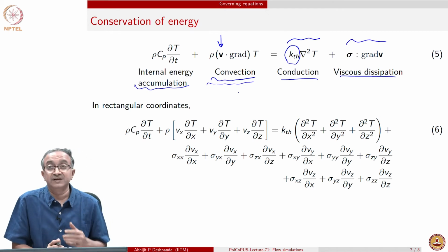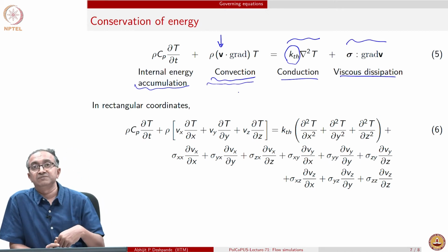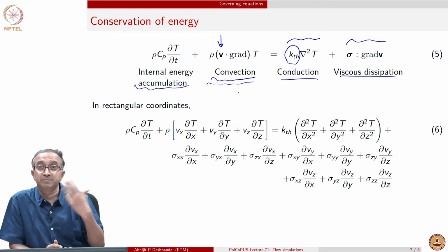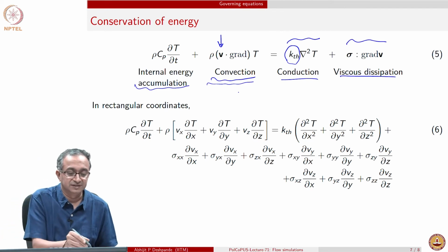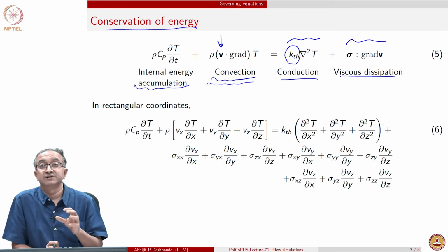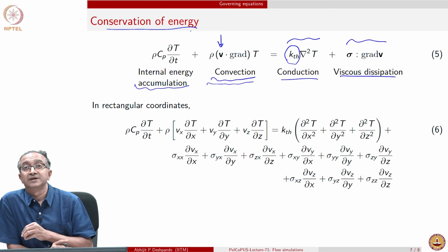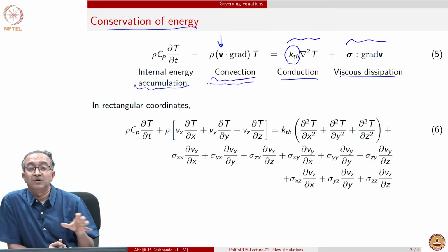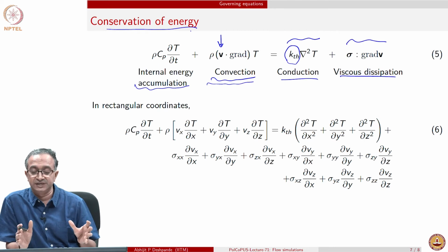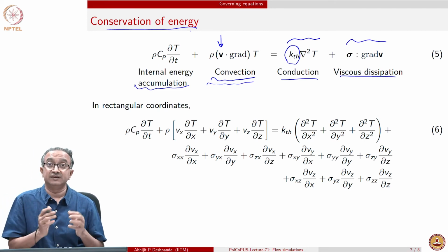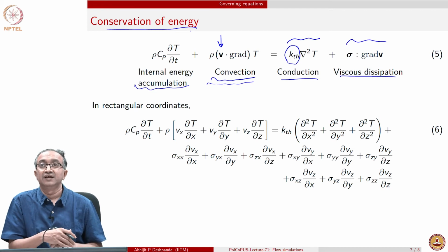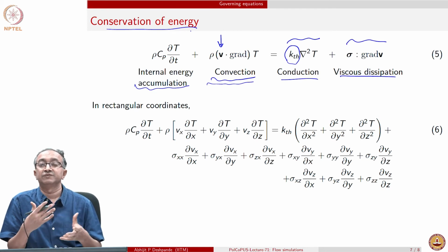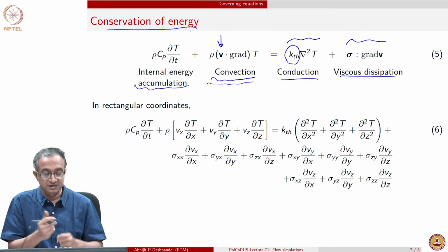At the same time, even convection may not be always easy to achieve, especially because turbulent flow and rapid mixing is not possible in case of polymers. So, you can see why there is a very great relevance for conservation of energy in polymer processing operations. With heating, cooling and all the other processes where temperature is changing and we have high shear rates and very high viscosity, the heat generated due to viscous dissipation can lead to non-uniform temperatures in the material, and non-uniformity can lead to different set of properties at different spots in a part.